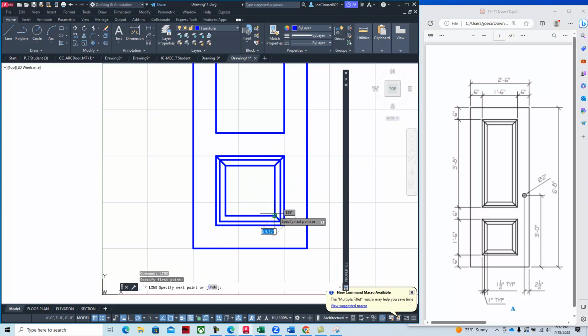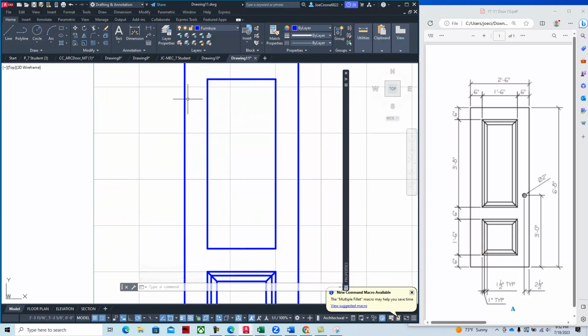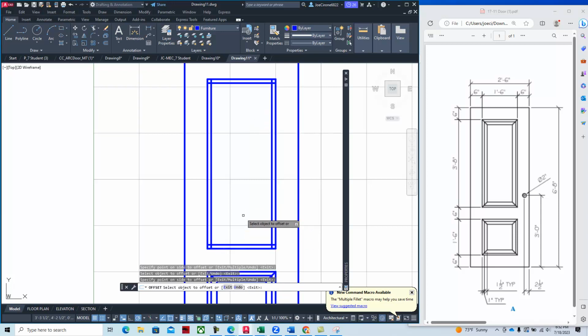And what I'm doing is I'm right mouse clicking after I put the geometry in there, and then right mouse clicking again to repeat the command. And that's the quickest way to create that shape. We're going to do it again up here at the top, and so we'll say offset 1, enter, line to the inside, enter, and then we'll fillet those with the radius of 0.